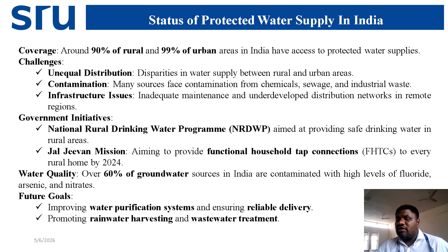Next will be the secondary treatment. Here we need to provide aeration, and bacteria will also be there. Bacteria try to degrade the BOD. In this process, it will be settled. Then some portion of the sludge will be sent back to the aeration tank to maintain the microbes as well as the organic matter. This way, the wastewater will be treated.